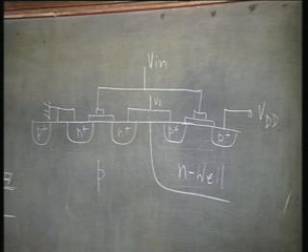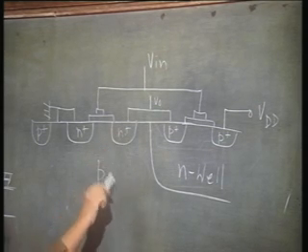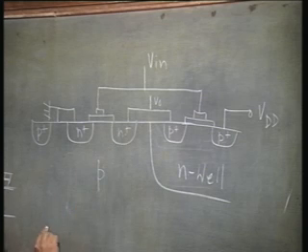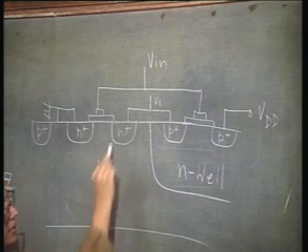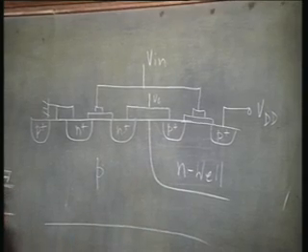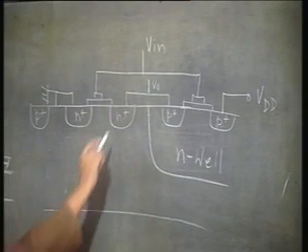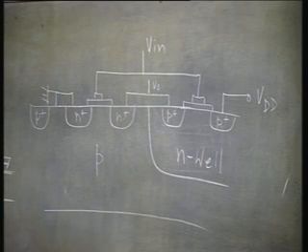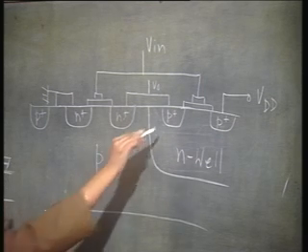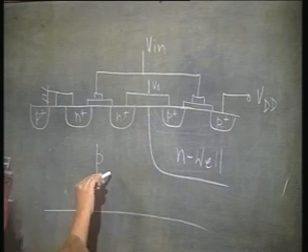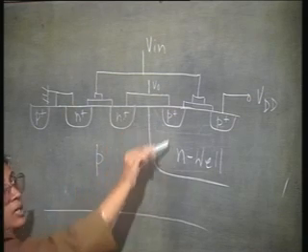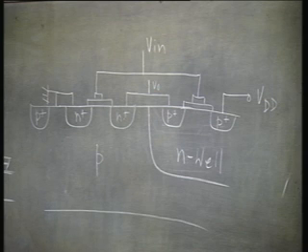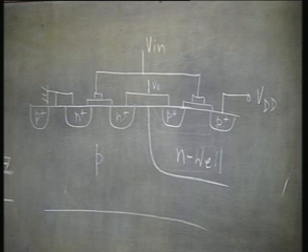Now, in this particular structure, I have two transistors as well, N, P, N. This N plus, this P type substrate and this Nwell, there is an NPN transistor. Similarly, this P plus, this Nwell and this P type substrate, I have a PNP transistor also. I have both an NPN transistor and a PNP transistor.